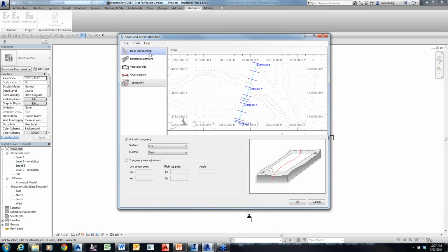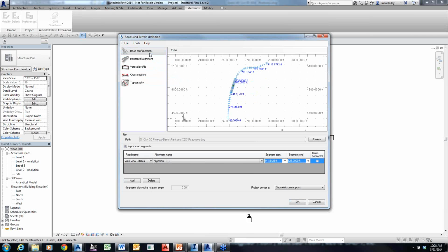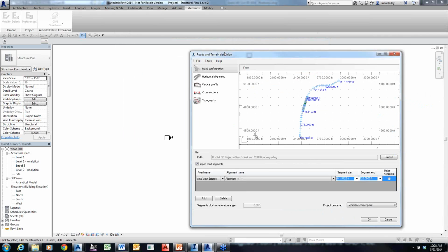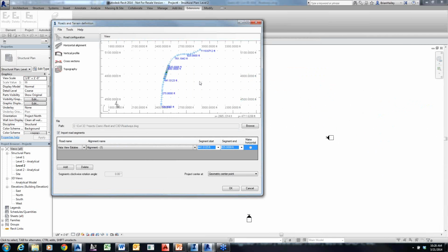And then there's another thing that we're going to point out, which is what happens when we bring it in here. It's going to center this topo surface on my origin point in Revit. And that's the default that's set up in the bridge tool. That's the one that Brian and I at first were struggling with, because we were expecting to get this to coordinate and have some coordination between it, and it didn't quite do it right away.